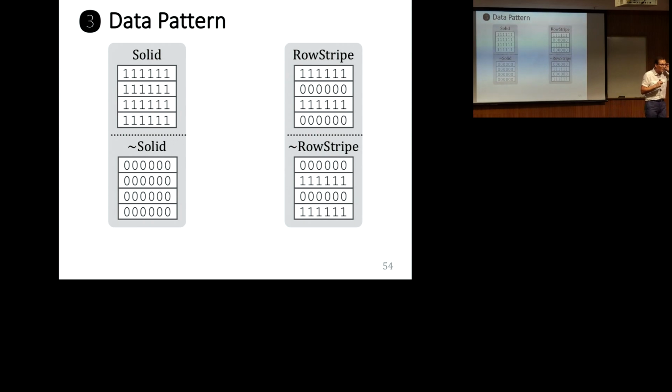And 1 is encoded as charge state in many cases. It's not VDD necessarily. The pre-charge voltage is not necessarily your power supply. It's VDD over 2. No, it's not. It's some reference voltage, basically. Maybe it's not necessarily that, but depending on the sense amplifier design, of course. But it's some reference voltage. But this is not related to pre-charge, right? This is related to charge loss in the end.